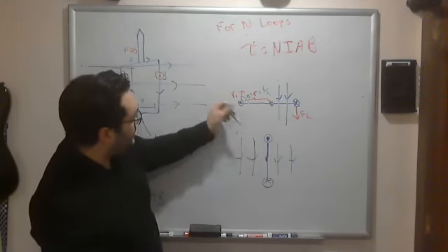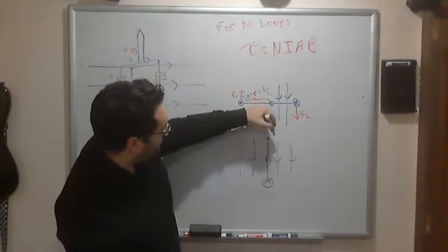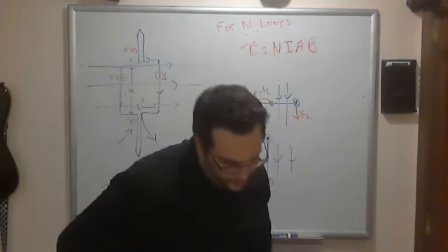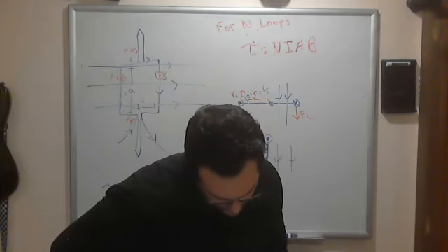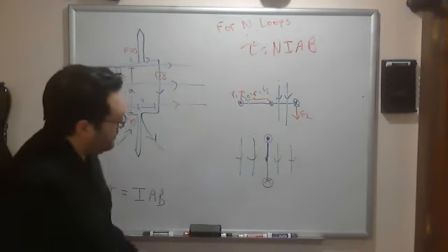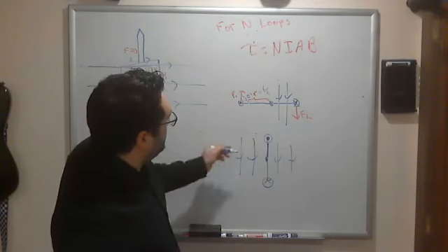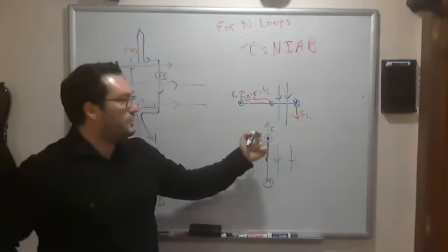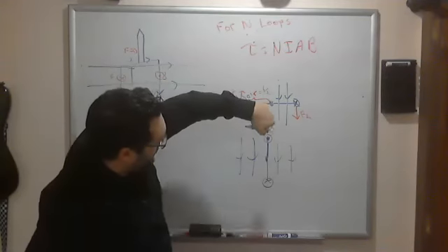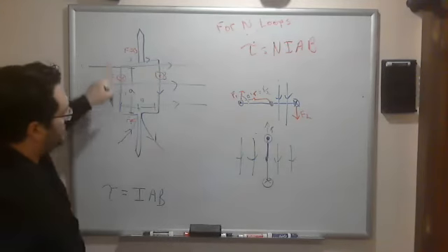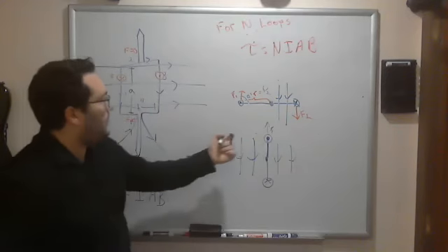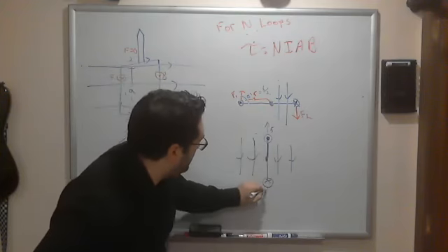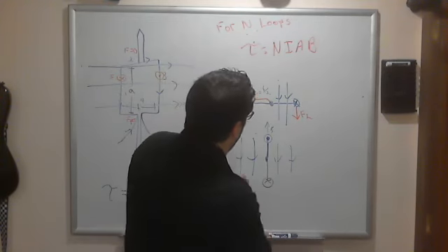If we rotate this up, the force over here is now in the same direction. The force is upwards over here, because the current is going into the page over here. This is this section, this is at the top. Oh, I'm sorry, out of the page. And then over here, it's going into the page. So the force is along the same direction. Let me write it like this.